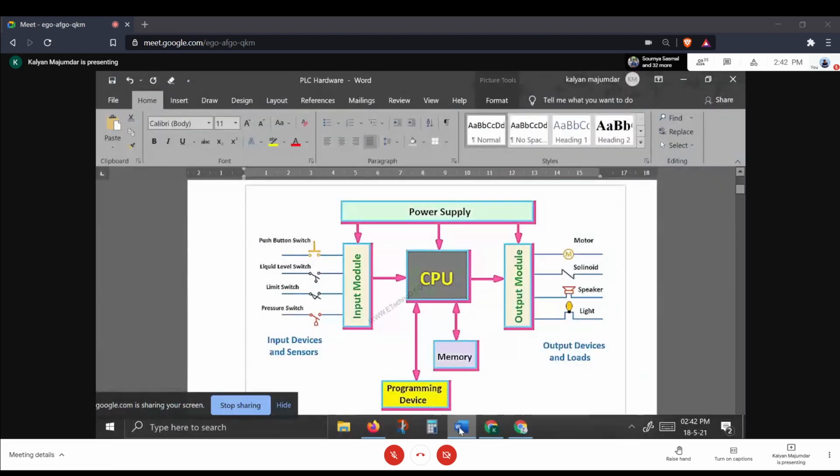Now, actuators, for example, you had your pump being operated by the PLC. It was being turned on or turned off. That is one output device. It could be a solenoid valve, or it could be control valves that have an analog output. So you could have various kinds of devices. It could be a motor being turned on or turned off. So again, the PLC must have the ability to directly connect to output devices and directly connect to input devices.